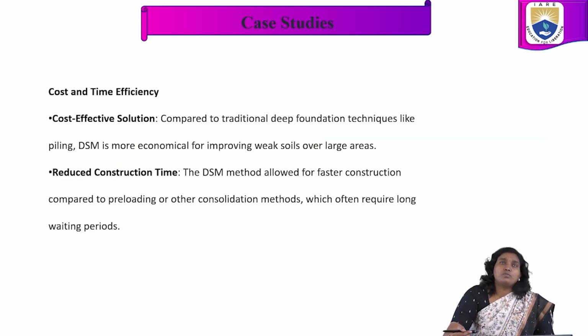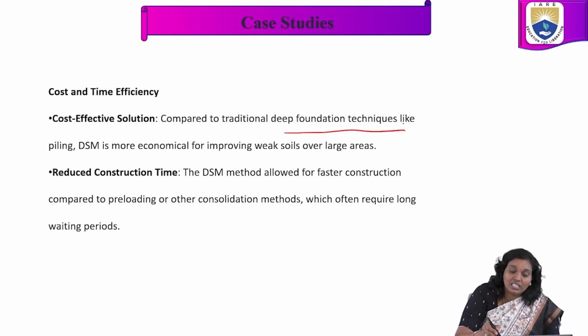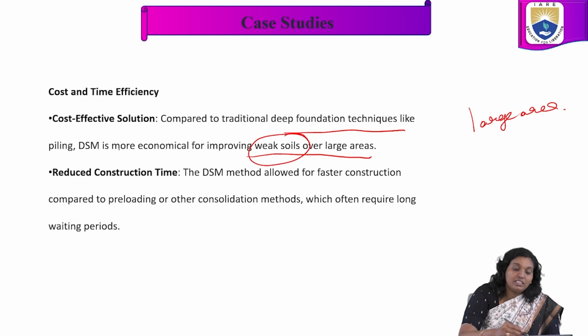And in terms of cost and time efficiency, it is a cost-effective solution compared to the traditional deep foundation techniques like piling. DSM is more economical for improving weak soil over large areas. So whenever it is for large areas in weak soils, this deep soil mixing is the suitable one.